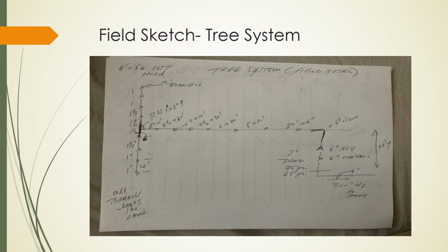And so what I am doing is, for me, I'm starting at the riser, identifying the distance from the riser back out to the street, and I know the pipe size. I use my laser pointer, or there is a variety of other tricks too. If you don't have a laser pointer, you can count these CMU blocks to establish the height. There are a variety of tricks that we would use to establish what the height of the building was.